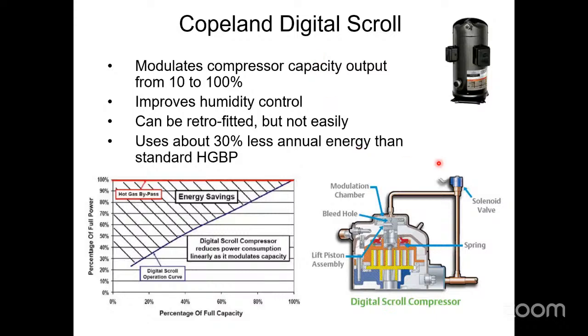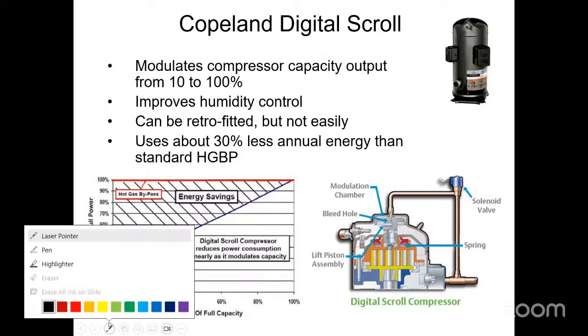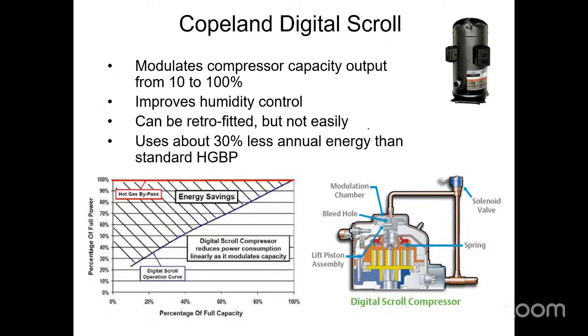So fundamentally, what it does, if you don't know how a scroll compressor works, I probably should get a video of it or something, but we'll see if my pen doesn't do anything weird on me. If I was to cut the top of this compressor off and look inside it, there'd be the scroll flange on the top and on the bottom side of it. So there's a scroll like that, and then inside there, there's another scroll for the bottom piece, and they're intertwined.